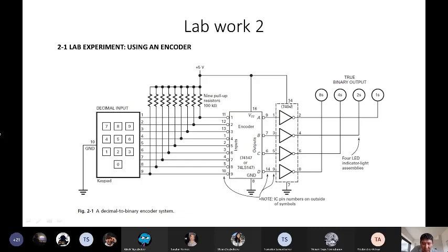For this reason, we need an inverter. Here you can see the inverter. What is its task? For example, if on pin 9 you get 0, the inverter gives us the complementary, opposite state: it will give us 1. If here we have 1, it gives us 0. The triangle is the inverter, yes? Yes, 7414 is our inverter.